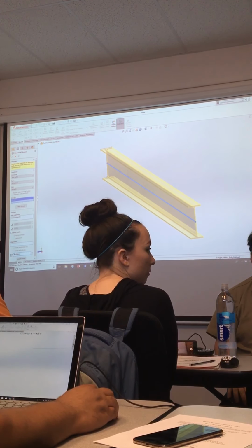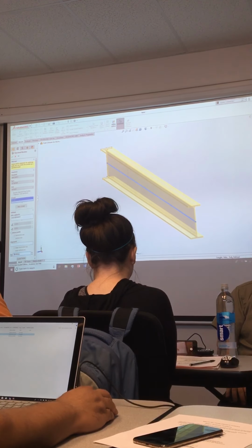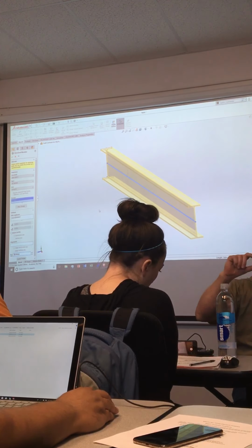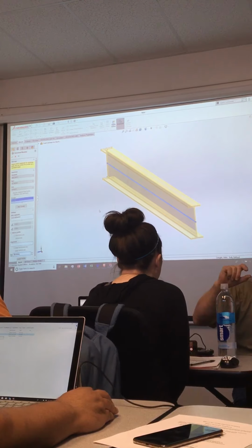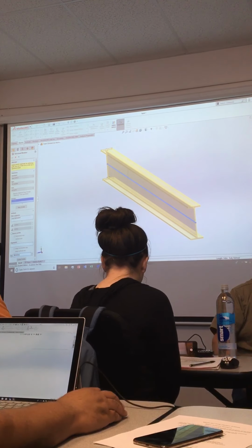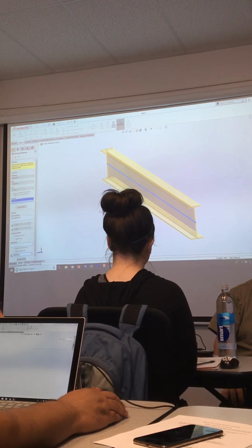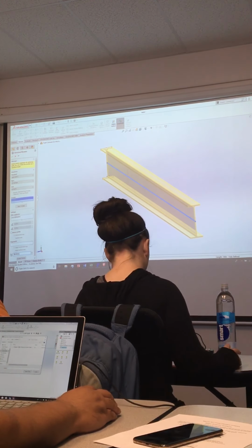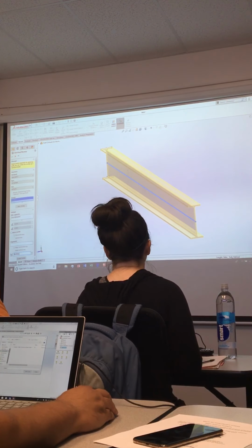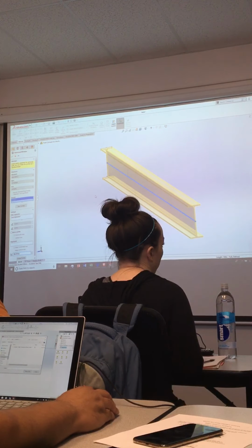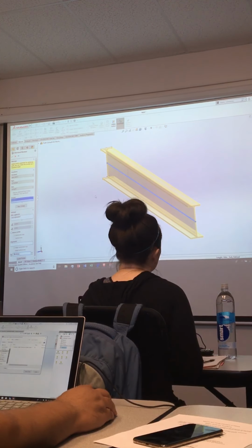The W sections and the HP sections and some of the other newer sections all have flat flanges. They're all constant thickness all the way across, and they're the ones that we all use these days. They're much cheaper than the S sections for a variety of reasons. So anyway, you can pick an S section if you want to follow along. Later you can just go back and change the profile and it'll all work, right?